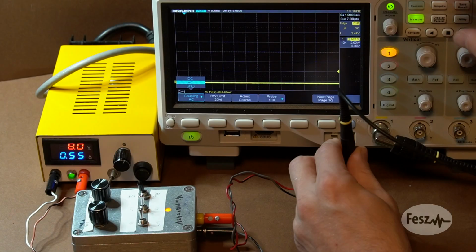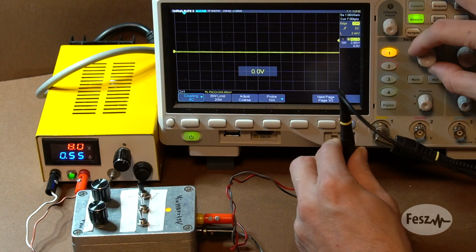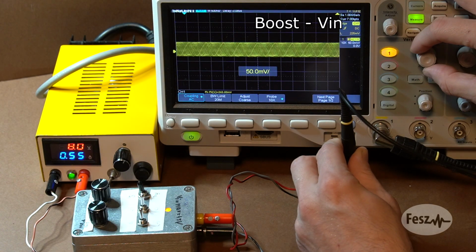So far, we strictly focused on the switching node, which is supposed to switch and be noisy, to some extent at least. The large amplitude variations of the switching node will also be observed in the near field using electrical field probes. It's not something you want to see, but it will be there unless some special measures are taken to reduce it.